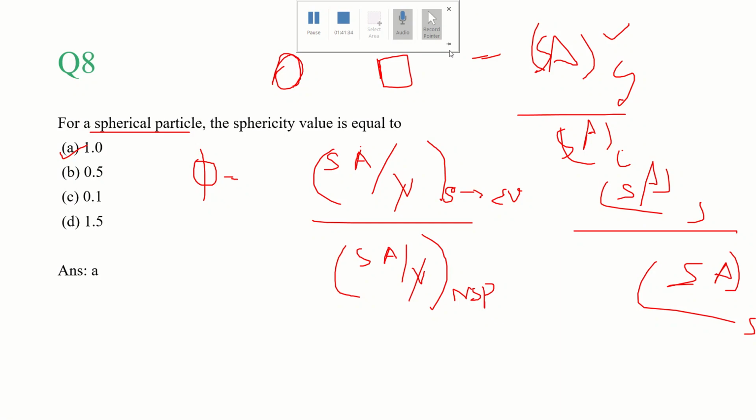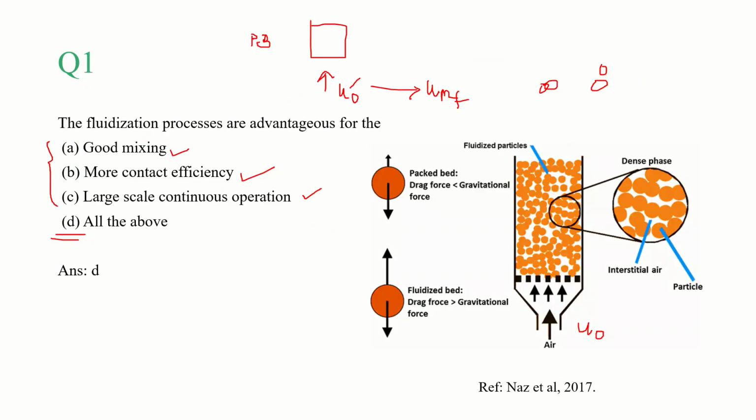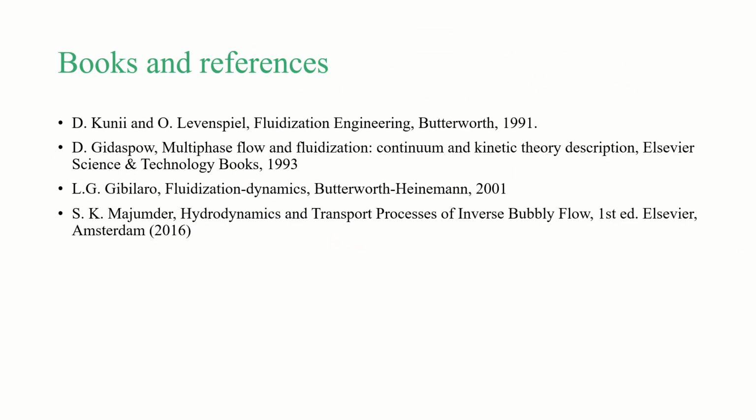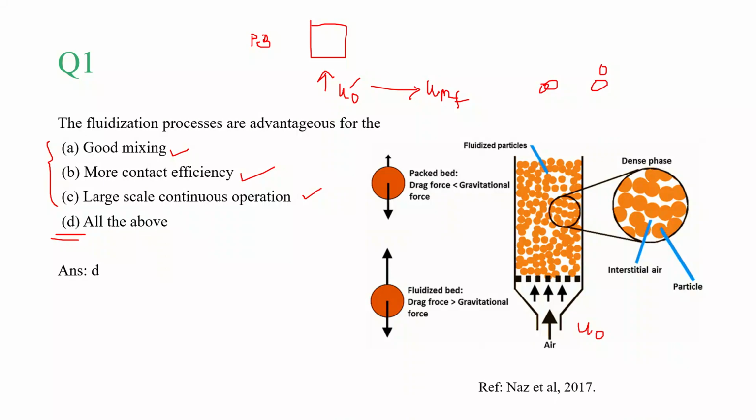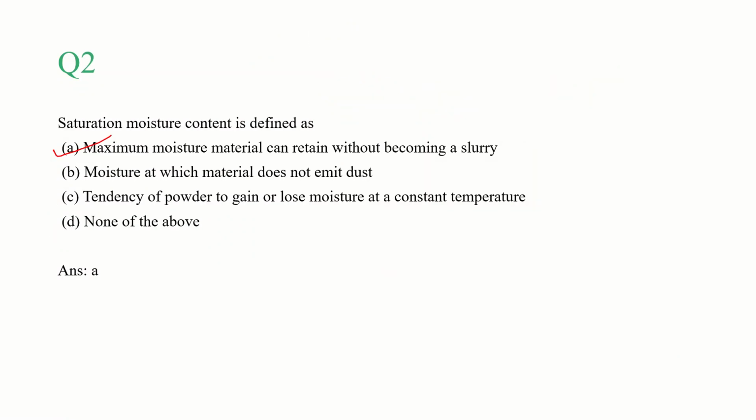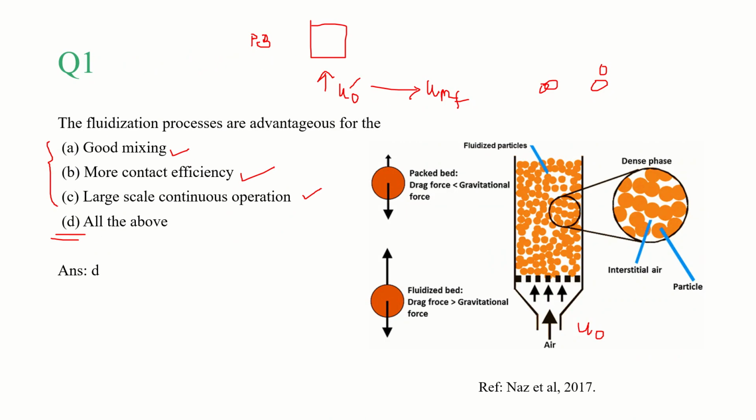So that's it for today's session. In today's class, we saw a few problems associated with the fluidization course from the first week lecture. We discussed the overall fluidization process and different terminologies associated with fluidization, and then we saw a few parameters like sphericity, circularity, and so on to define non-spherical particle shape. And then we saw a few regimes of fluidization like smooth fluidization, bubbling fluidization, slugging regime, churn fluidization, and pneumatic transport or lean phase fluidization.